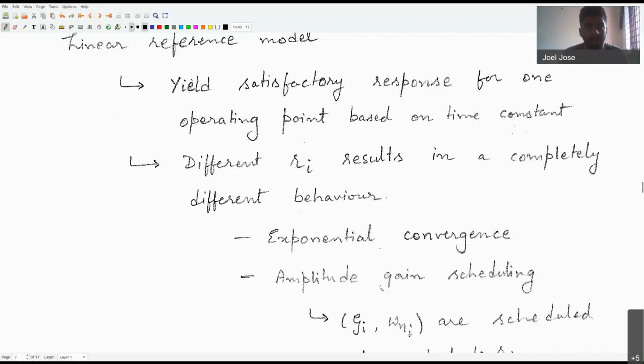Like that much amount of thrust cannot be given by the ship. So in that case, for a limited amount of reference signal, we can give an expected omega and damping. But for higher amounts of the reference signal, we have to give a higher damping or some different values of omega and damping in order to compensate for that.